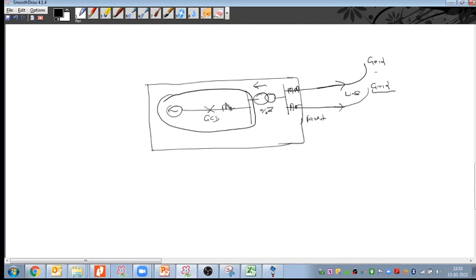Yes, I was talking about the fault current coming here, which we can call the through fault current, that is one point. Or we can take how much this generator is contributing fault current based on its transient reactance, the Xd value. So which one is higher, that we can take. When it comes to this location, there are two approaches. We can find out the short circuit contribution by the generator and take that, or we can calculate this through fault and see which one is the higher fault current, and consider the higher value.